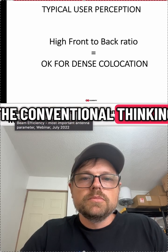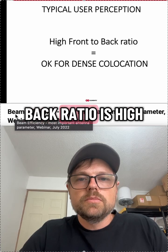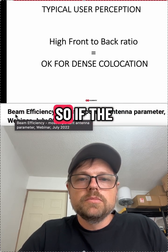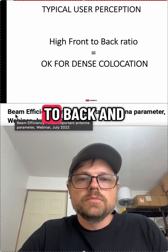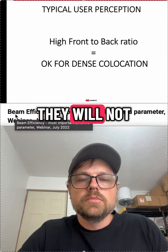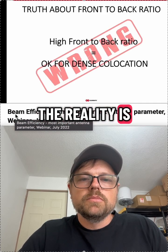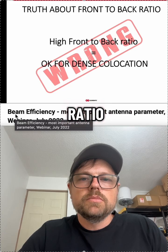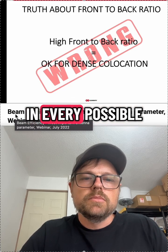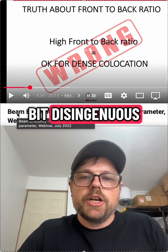The conventional thinking about front-to-back ratio is that if the front-to-back ratio is high, it means an antenna is good for dense collocation. So if the antennas are back-to-back and both have high front-to-back ratio, they will not interfere with each other. The reality is that high front-to-back ratio does not mean that antenna is good for dense collocation in every possible setting. So I just find this to be a little bit disingenuous.